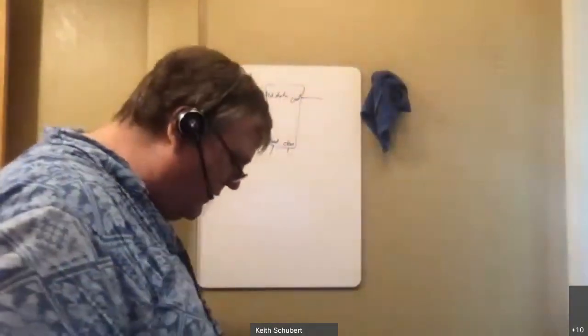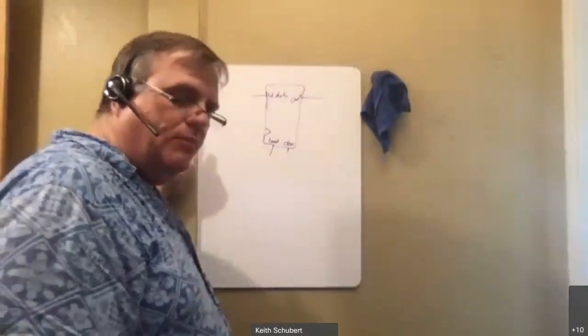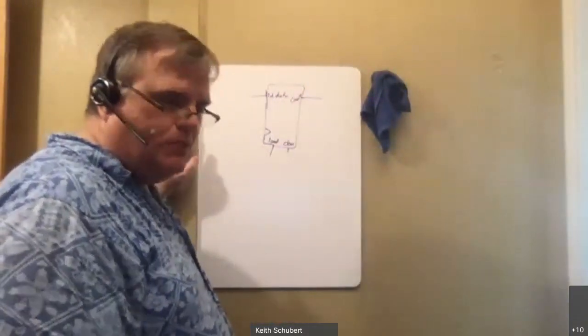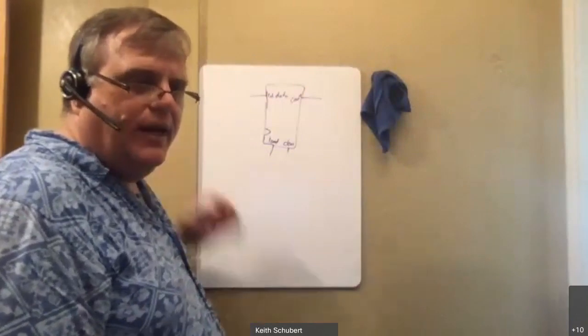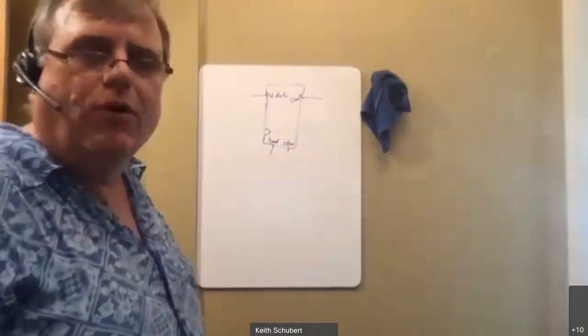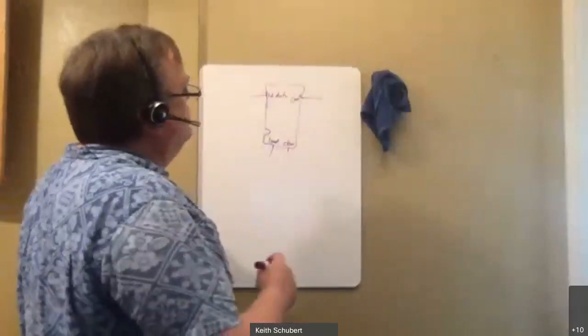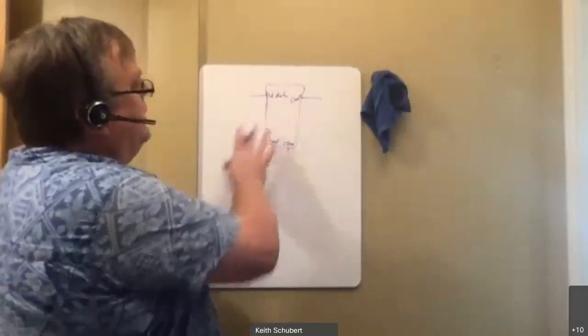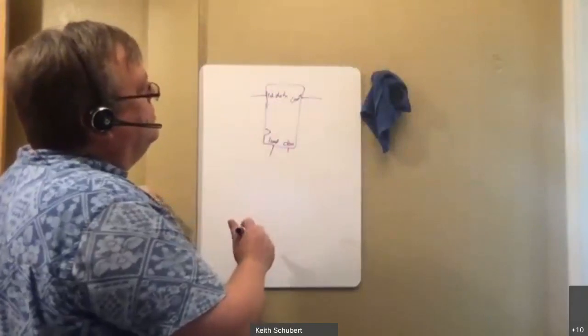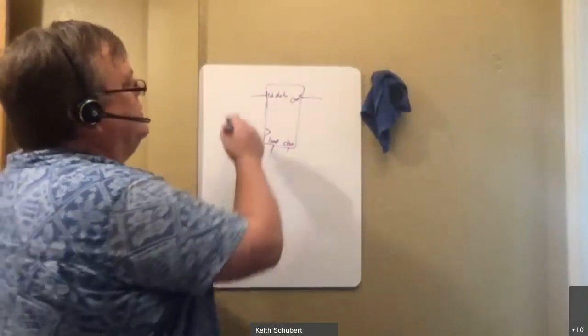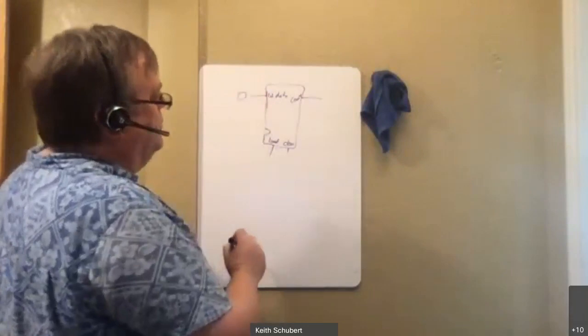All I'd have to do is make that mux a little bit bigger, and I could have a count up state and a count down state. And I would pick one of those as a default. And then you could have an up down count that tells you which way you're going. But right now, this gives me my basic up counter, which, like we said, we can then just put zeros on my load data.